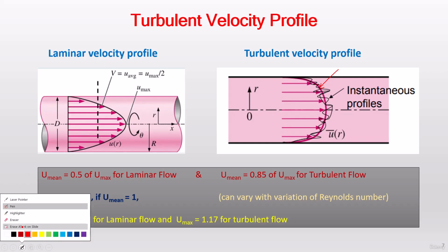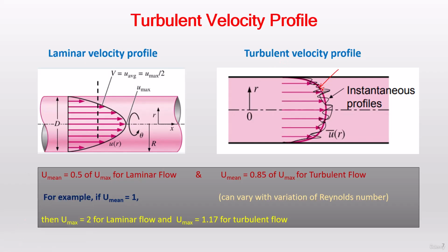Now this means that if I want to predict turbulent flow, I have to not only solve, like we do in laminar flow, the equations for the velocity profile like du by dy, or du by dr actually. We write it as dy because we are solving in xy coordinates, but the y coordinate is actually representing the radial coordinate, and x is in the axial direction. So that is when you solve the problem as two-dimensional; otherwise in three dimensions everything is x, y, z. So here we have to take care of this change as well. That is called the fluctuating component.